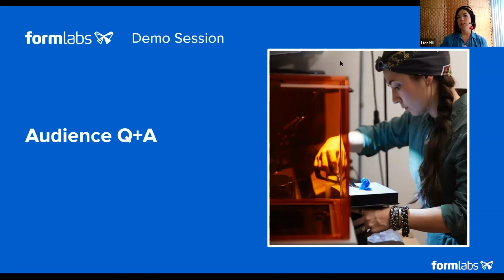But if you decide to print production, just pull the build platform out of my printer. If you decide to really fill up the build platform full of production pieces, and that is going to then go to a casting house, you would want to print that in castable wax. You cannot cast from gray resin. You can cast from castable wax resin.